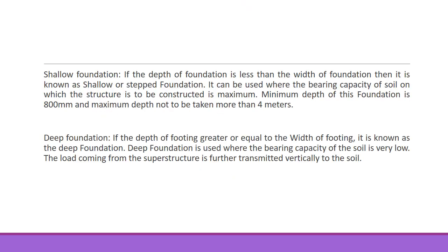What is shallow foundation? If the depth of the foundation is less than the width of the foundation, then it is known as a shallow foundation. It can be used where the bearing capacity of the soil on which the structure is constructed is adequate. The minimum depth of this foundation is 800 mm and the maximum depth shall not be taken more than 4 meters.